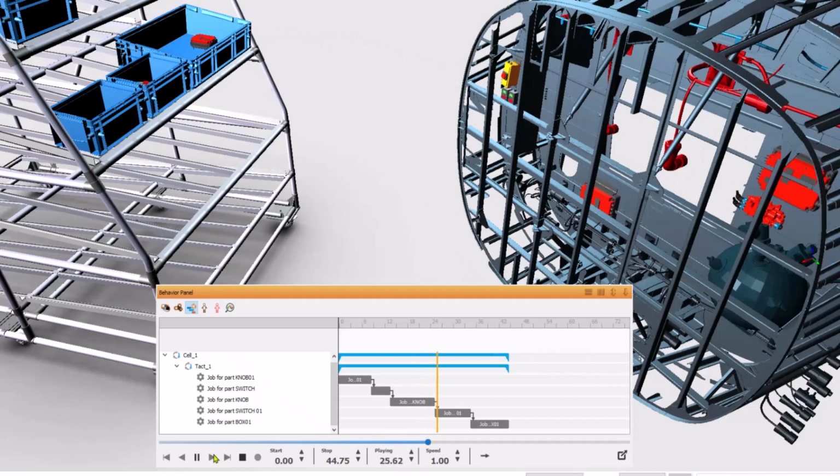Upon review of the assembly order, maybe we conclude that the assembly is suboptimal. In this case, the last object to be installed is the furthest one in, and I have to reach past the other objects in order to install it. And maybe I would decide that it would be smarter and easier to make sure that the first thing that I install is the furthest in that I have to reach. And that way I'm not reaching over already installed components.